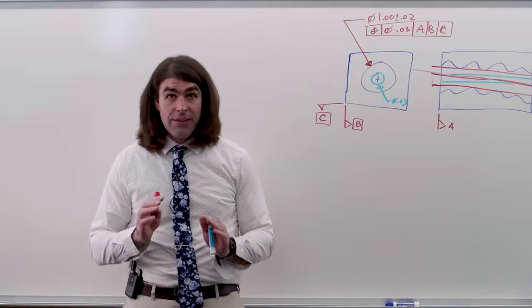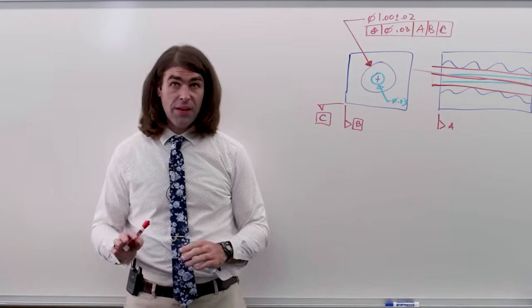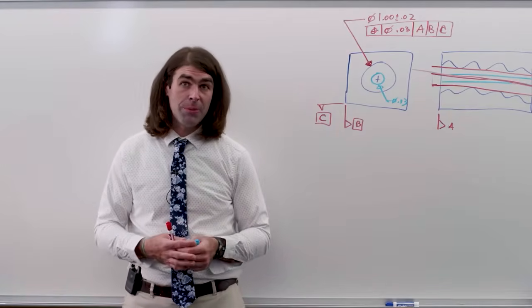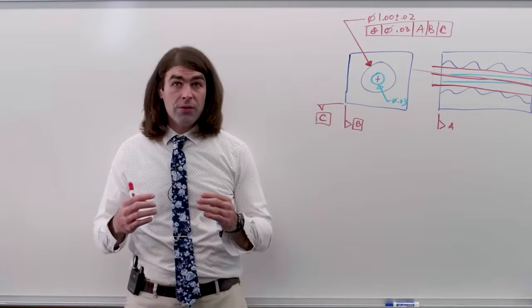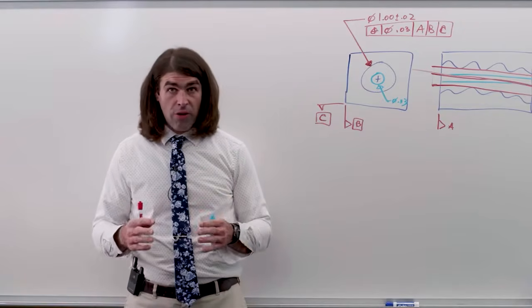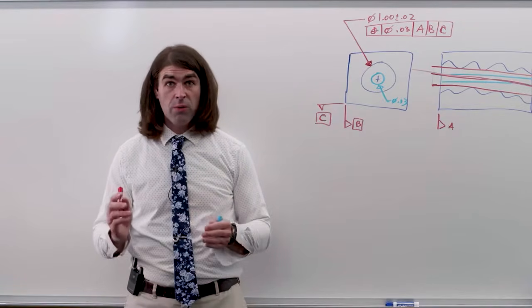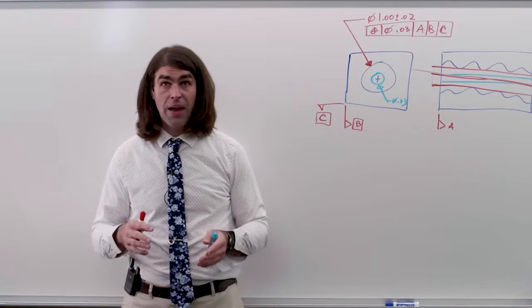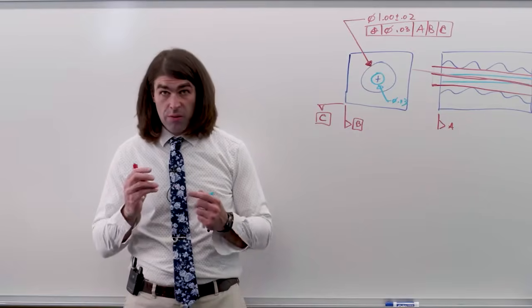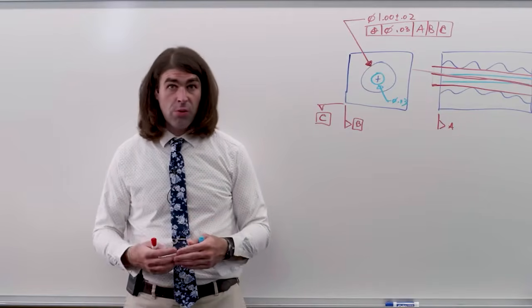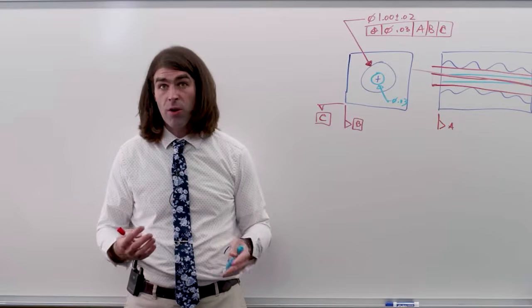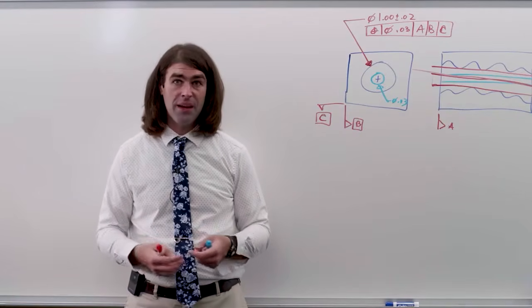But that's the big difference between position tolerances and basically all of the other tolerances, and that's why some people have difficulty with it, because you're not really measuring all of the feature. You're only considering what really matters, and it's a very powerful thing to apply to a drawing. And then later in this video, we'll get to applying MMC and LMC and how you can get even more tolerance with this concept, okay?